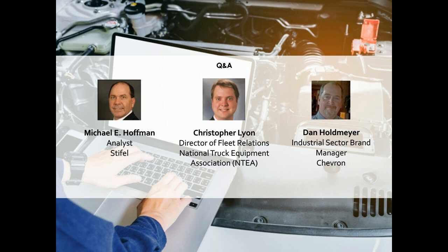So do some homework, ask the questions about what kind of cleanliness level will you deliver my hydraulic oil, and what do we know about the engine oil specifications. Have them review your fleet to make sure they know what your fleet requirements are, and they'll make the recommendation on what product should be used in there. It's not just a matter of saying, okay, I've got this oil, it's 15W40, here you can use it in your entire fleet. There are differences in the equipment, what they require, but also, as Chris was just mentioning, review your own personal or your company objectives.